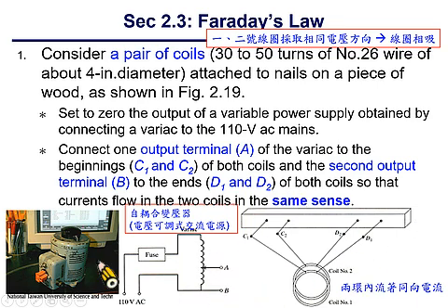Okay, so you want to gradually increase or decrease the power provided to the coil, because once you connect the coil to the variac, you will provide relatively large currents in the loops.